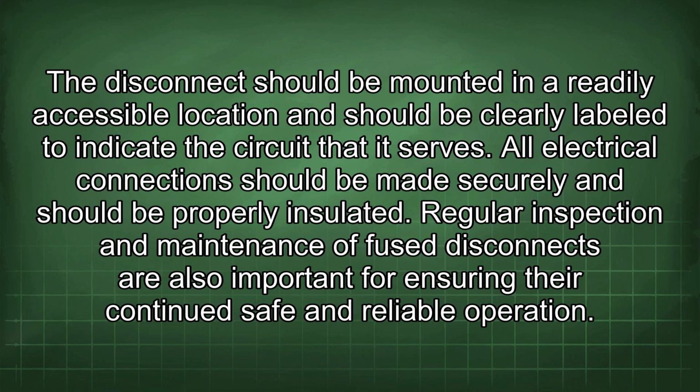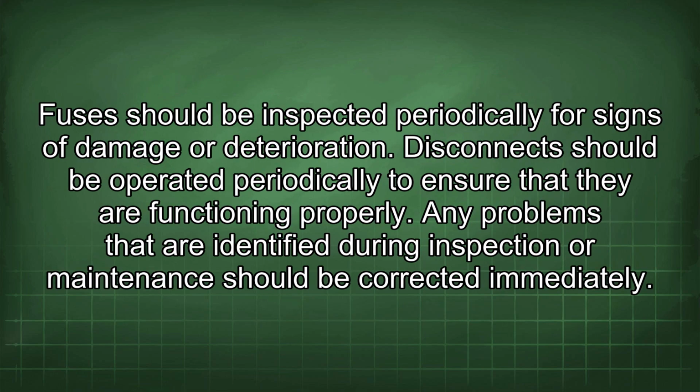Regular inspection and maintenance of fuse disconnects are also important for ensuring their continued safe and reliable operation. Fuses should be inspected periodically for signs of damage or deterioration. Disconnects should be operated periodically to ensure that they are functioning properly. Any problems that are identified during inspection or maintenance should be corrected immediately.